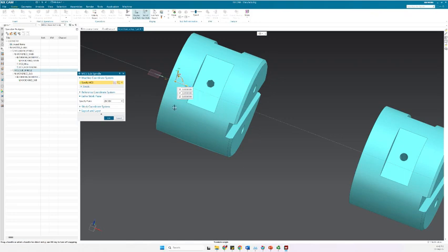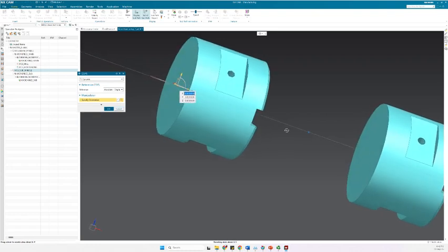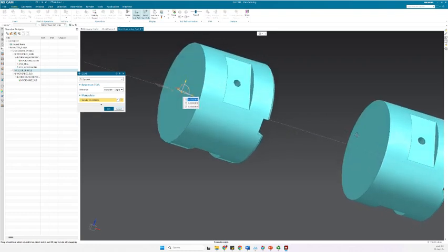So now what I would like to do is actually to specify this coordinate system. Pay attention that this is on the ZX plane of the machine itself, and then clicking here. And now I need to define it here, and to be able to define it clearly, I will just see if I can use infer.